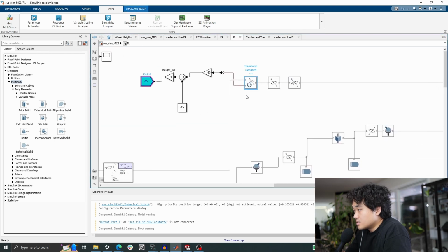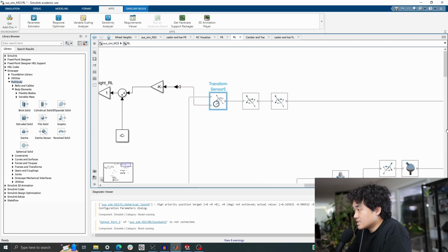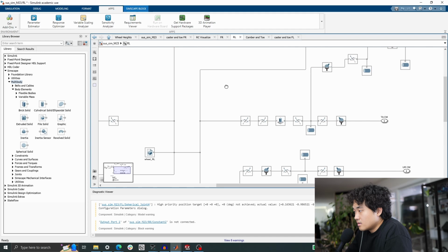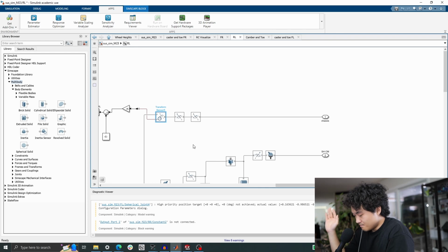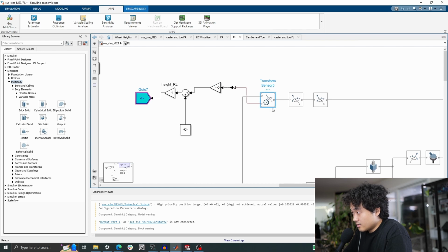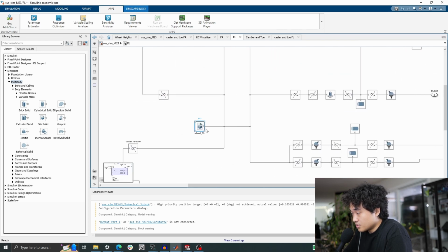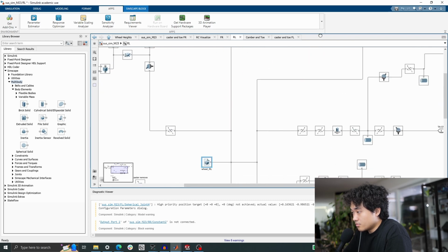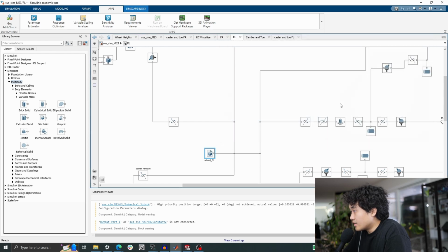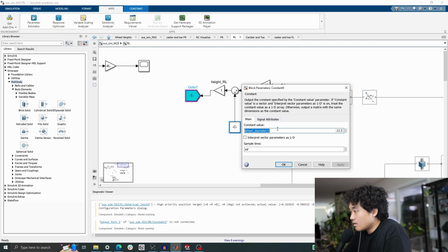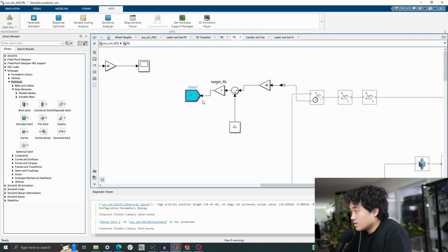Let's see where that comes from. Right, here's a transform sensor. Your base is the chassis, or a point on the chassis. In this case, specifically the lowest point on the chassis, which last year was 2 inches below the chassis origin. So I accounted for that. Your follower frame is what? Let's see where that goes to. That's the wheel, right? So it goes to the center of the wheel. That's where the R frame is, right? But in order to get to the bottom patch, I just added the tire radius, half the diameter, and you get basically the right clearance, the right height.